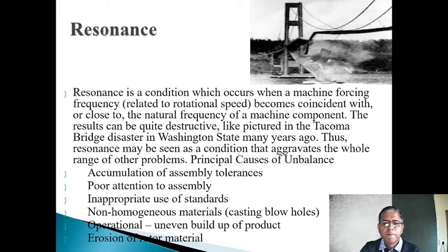Next is resonance. Particularly, structural members are very prone to resonance, so structural design engineers take utmost care to avoid it. Resonance is a phenomenon when the natural frequency of the structure matches the excitation frequency, and because of that, the amplitude of vibration becomes too much, and the member fails.